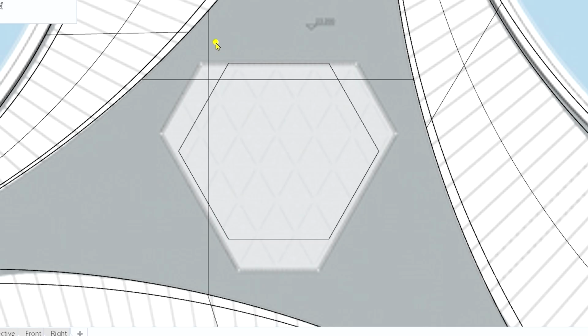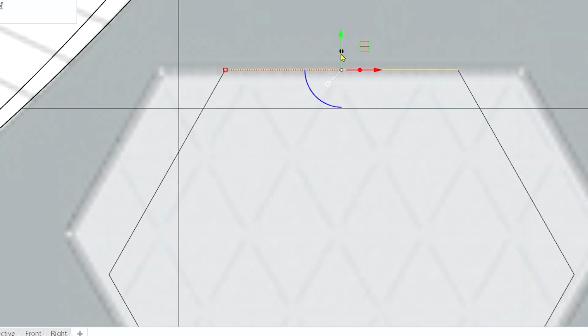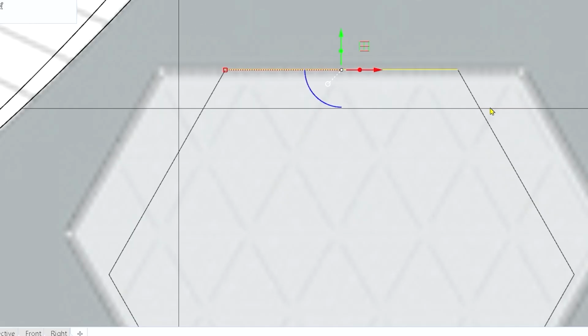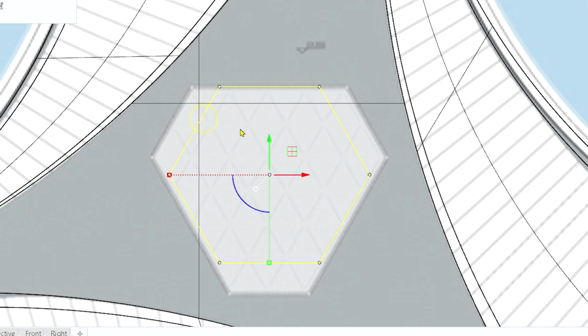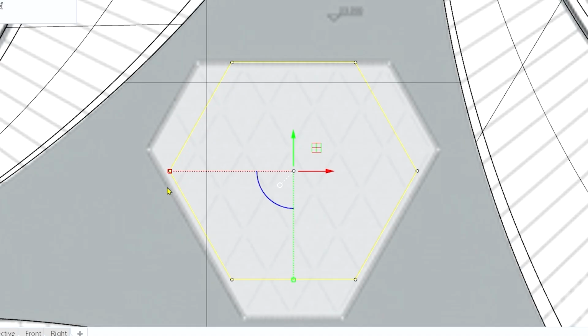Now you can see these two control points. I will select them with control shift, select these two, and use this red square button in your gumball, make sure your gumball is on. So how does it help? If you just click this and drag and hold the shift key, it will drag in 2 dimensions, right? Or if you select control shift and use the shift key and then drag, it will go in the same proportion, but in scaling it helps. Let's say I will show you. Let's say this whole polygon, a hexagon, you want to scale in proportion.